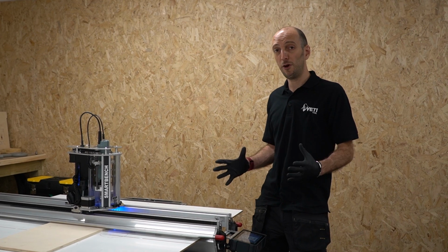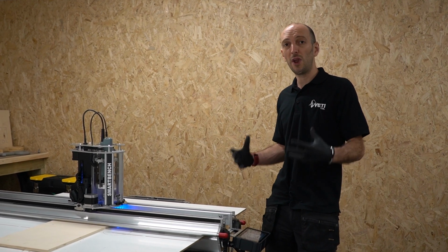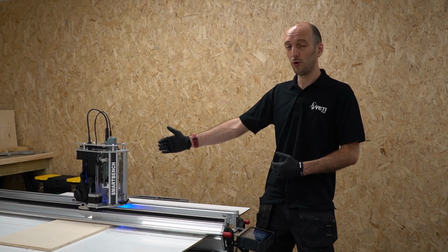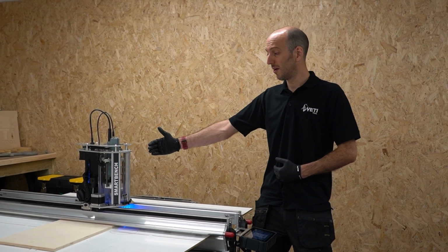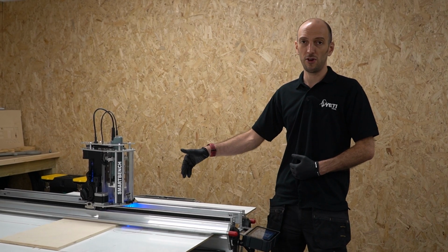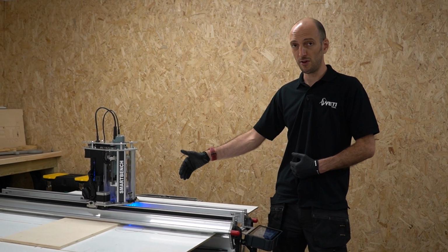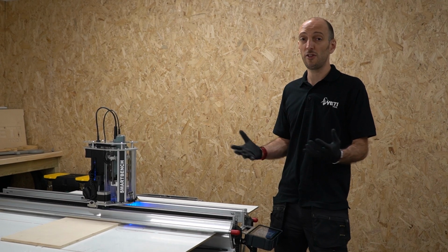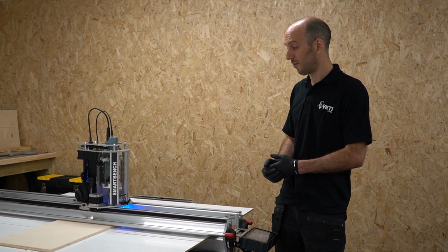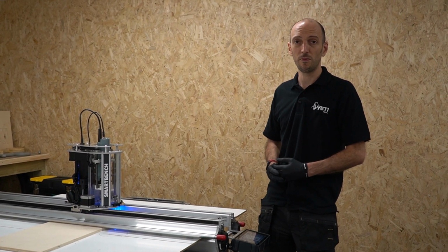I'm going to confirm by pushing yes now. And when I do, because I'm using the laser datum, SmartBench will automatically move the Z head so that the tool center is over the exact position of the working datum location. This is really just a visual check to make sure that the Z head will start from the position I expect it to.